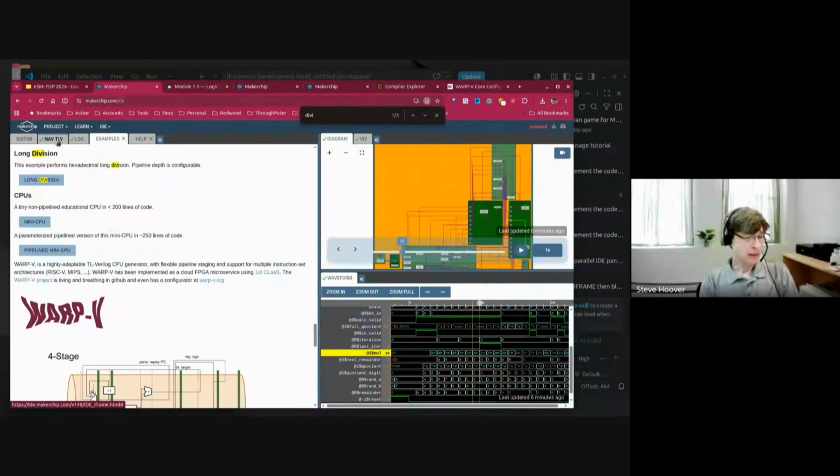I decided to layer my new methodology on top of RTL because I didn't want to inherit some of the baggage that's inherent in the high-level synthesis tools. And it's a more broadly accepted technology. You also have the baggage that the goal of debugging with high-level synthesis is to leverage the C++ ecosystem. So you're using GCC as a hardware debugger, which is a very awkward prospect.